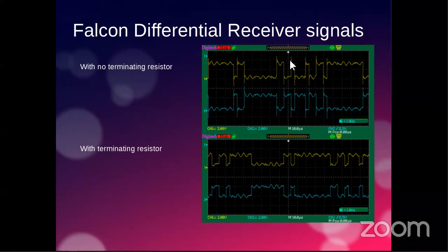So if you're using the smart remotes, setting those termination switches appropriately on the last smart remote in the chain is really important if you don't want to have signaling reflection issues, which you can see up here, and get yourself a much cleaner signal. And you don't want to be terminating it early because that'll screw you up even more.